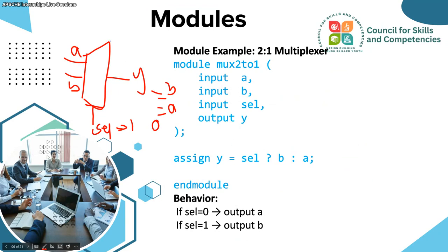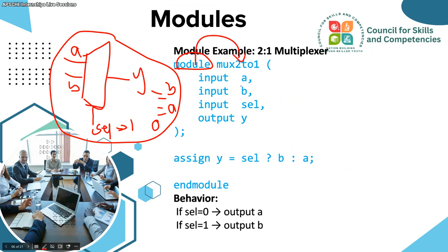That is the thing we are going to design in Verilog. How do I want to create it? I want to write a module. The module has been written and I am giving the name my multiplexer, so by the name I can understand it is a mux, a 2 to 1 mux, getting 2 inputs to 1. If you give a meaningful name, it will be easy to understand. And that mux takes 2 inputs, so input A, input B.